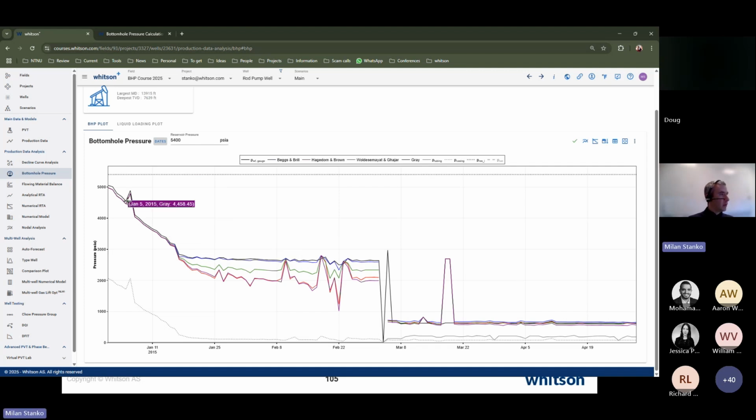And that's what I found. This is the gauge. Actually all of them are quite close. And here this began to deviate, but still Beggs and Brill apparently gives a good similar value. And here also the gauge is quite close to the prediction. But here you have something strange. This was your gauge, and here all of them are first overlapping and then going to a very high value. So what could be happening here?